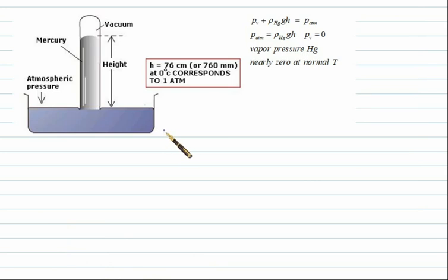If you want to measure the atmospheric pressure, that can be done with the help of a barometer. A barometer is just an inverted tube dipped in a mercury tub. So if we have a mercury tub here, this pressure will be the same as atmospheric, and as the z value increases, the pressure is going to drop. So this one is atmospheric pressure, and if you move above this side, the pressure will drop.